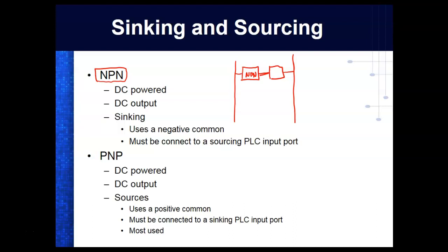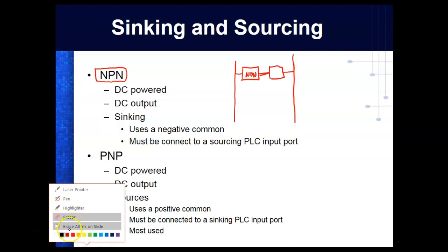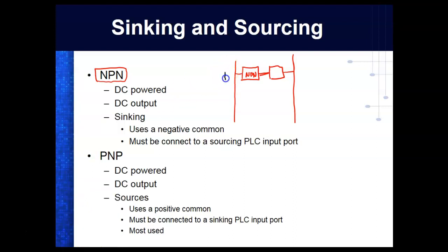Now, if I come over here and this is a plus, that means this is a plus common. So this over here has to be a minus. And now I have to use a PNP sensor. This has nothing to do with push buttons. Push buttons don't care what's negative and what's positive. Switches don't care what's negative or positive. Electronic sensors do care how you use them.